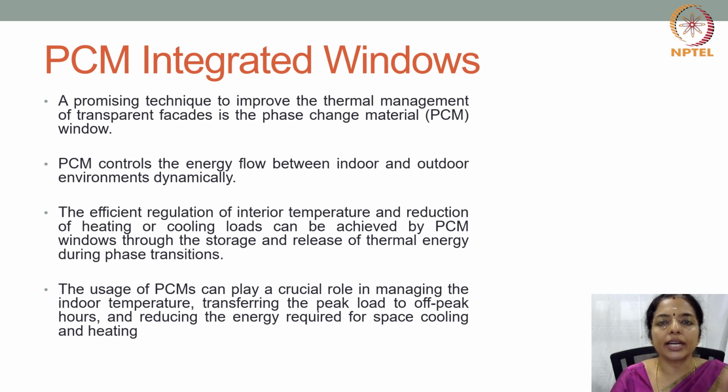The efficient regulation of interior temperature and reduction of heating or cooling load can be achieved by phase change material windows through the storage and release of thermal energy during phase transitions. The usage of phase change material can play a very crucial and important role in managing the indoor temperature, by transferring the peak load to off-peak hours and reducing the energy required for space cooling or space heating.